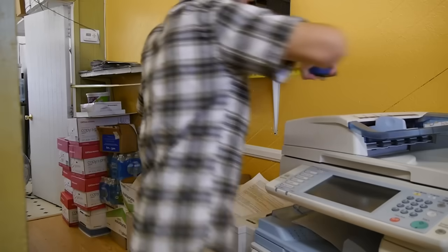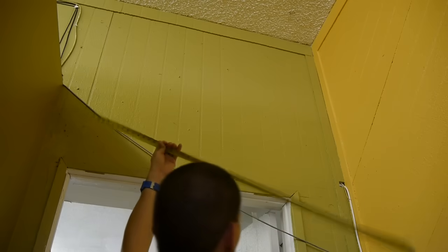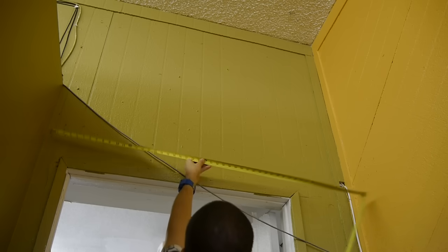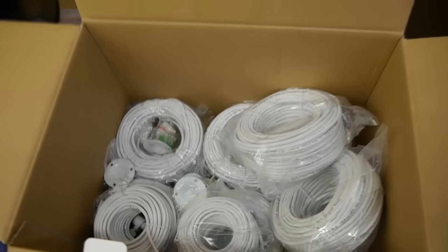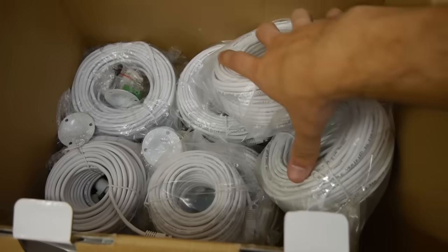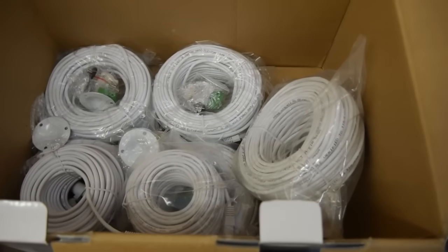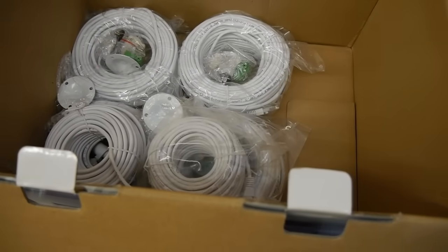The next step after you've figured out where you want to place your cameras and your DVR is to figure out how much cabling you're going to need to connect each and every camera to your DVR. Measure the distance between the location of each camera and your DVR to calculate how long each camera cable must be. Don't forget to also calculate the distance up and down the walls where the cable will run. Most surveillance kits come with long cables that should be long enough for small homes or offices, but if you need longer cables, now is the time to buy extra cable.